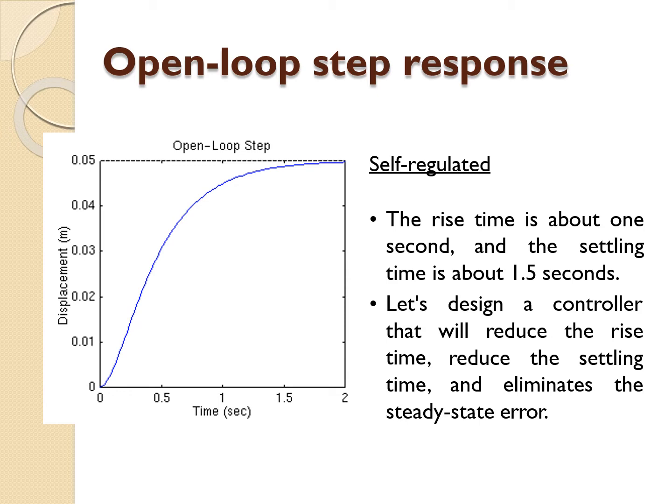So this is one example of a self-regulated system. For your information, a self-regulated system is a system that will reach a steady state. Steady state means it will reach a certain constant value at a certain time without having any controllers.